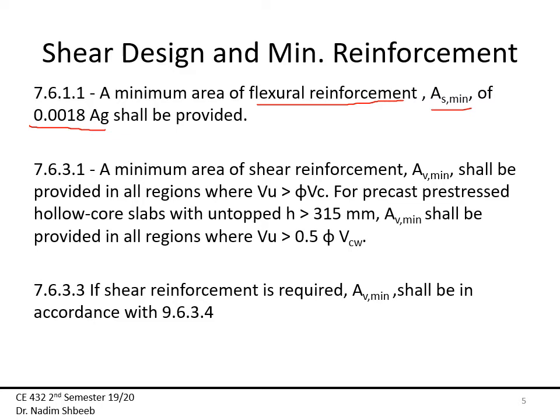All right, so these two, the rho minimum or AS minimum in the beams does not carry over to the slabs. Okay, so for the slabs, my minimum area reinforcement that is required is 0.0018 area gross, which means the gross area. Usually in solid slabs, when we do a design, we usually take a 1 meter width representation. It's usually per meter run. So this is usually 1 meter.